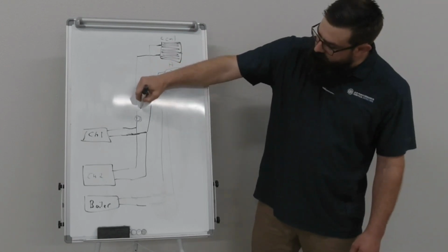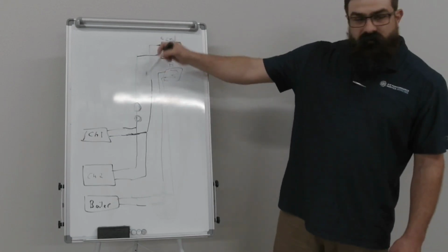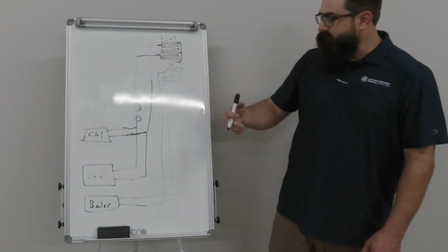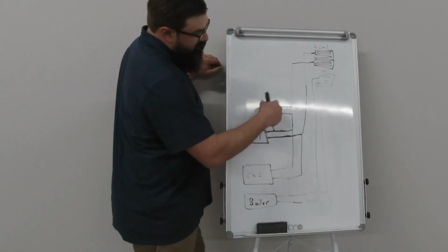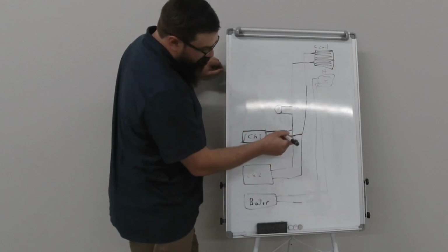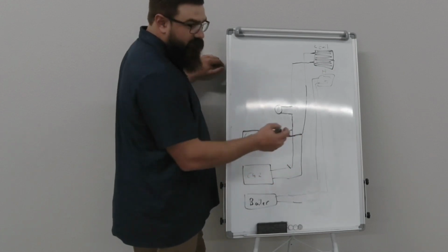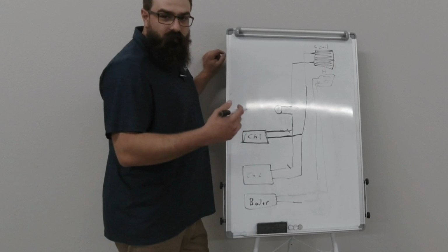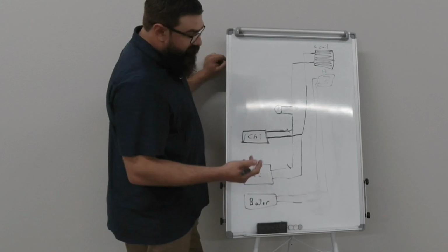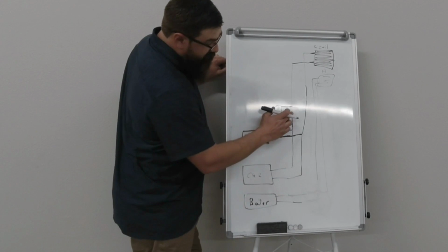Yeah, so you would have on dedicated, even on ones that have multiple pumps, they're all typically off of the header. From the chiller, the pump pushes, goes to the coil, comes back through, rotates. What we would have is a valve on one of these that could prevent flow through that chiller. That way you can only run one without pushing water through the other chiller. So on a dedicated system, instead of that valve being there, I guess the valve could still be there,